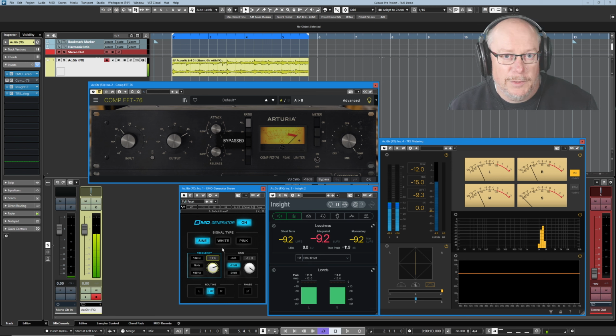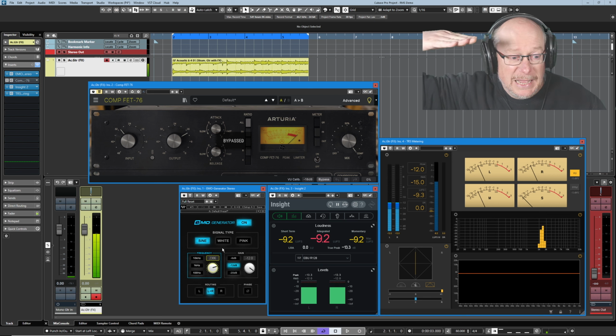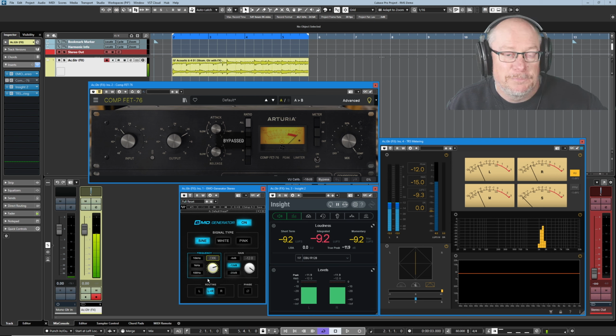So here's the first takeaway. If you want some sort of scientific norm across all of your test environments, be very careful with loudness. It's fundamentally dependent on the signal being fed into it. At the moment, we have an absolutely constant sine wave. That's going to produce very consistent results, but totally variant and completely dependent on the frequency that's being sent in. Okay, let's stick that in our notebook and move on to another kind of measurement.